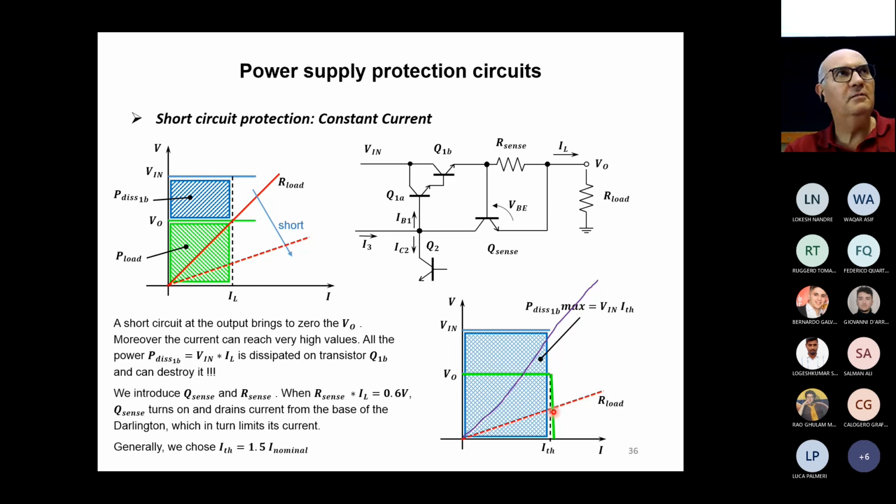But for batteries like the nickel metal hydride, you can use this situation because for recharging batteries, you need a constant current source, and you will charge your batteries for typically 14 or 7 hours or something like that, 10 hours. But you know how much current you're sending, you know the capacity of the battery, and you just make your calculation and keep this situation for charging the batteries.